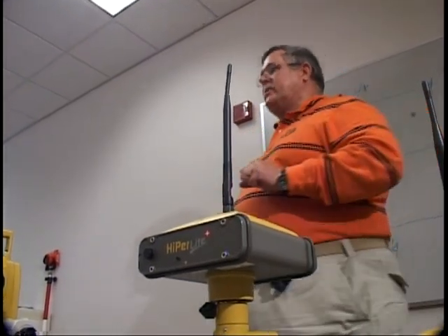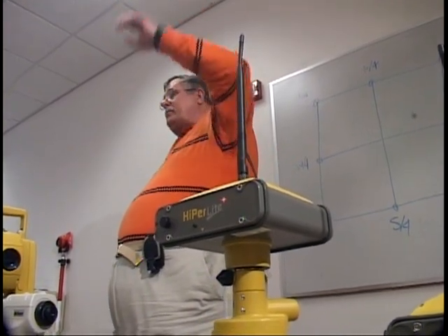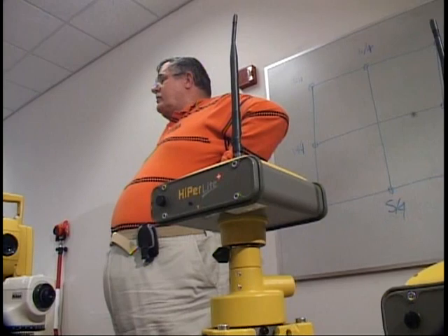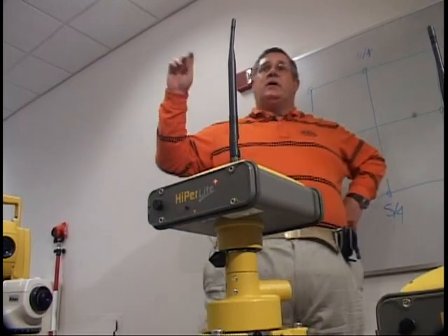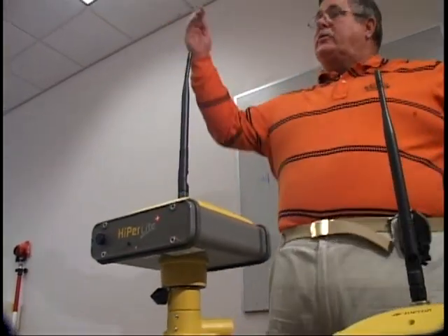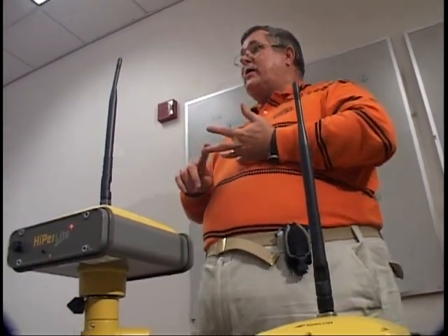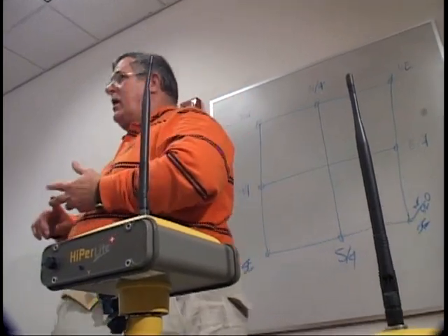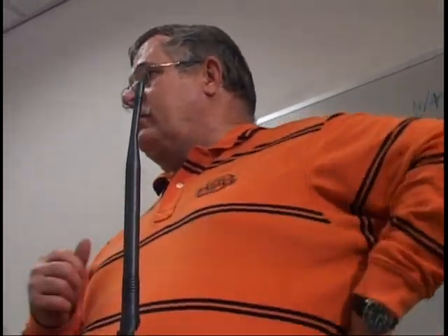On a GPS system, you have one part of it that sends a signal up to the satellites. You want to have at least 3 satellites that you're recording the information from. It'll send back information to you and very accurately tell you what the X, the Y, and the Z coordinates are. It is just a tremendous step forward in surveying technology, but one of the challenges of it is you do not have the ability to very quickly check to make sure that all your locations are correct.